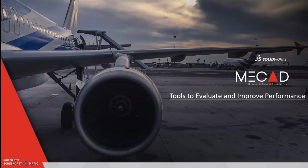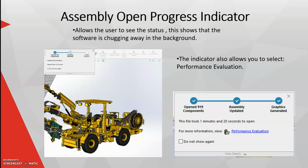So next, we're going to look at tools to evaluate and improve the performance. SolidWorks has some built-in tools and some features that actually allow us to follow a very nice workflow. And it actually shows us, okay, what is wrong with our assembly? What is taking time? What can we improve on? So from here, you'll see the assembly progress bar, right? This doesn't have anything to do with improving your performance, but what it allows the user to do is actually see the status of opening the assembly.